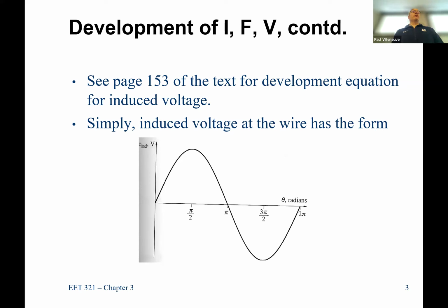Harmonics usually are bad because they don't necessarily do what you want them to do. So as much as you can, you try to just have your fundamental frequency. It's the same thing in motors, but motors generally are so good at putting out clean 60 hertz that there's never been a parameter called THD that I'm aware of for production inside of a synchronous machine or an induction machine.